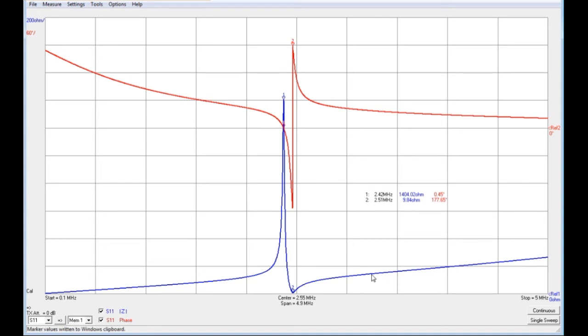So now this is typical of the characteristic of a primary coupled Tesla coil, so two resonant coils together. Obviously the self-resonance of the primary, I haven't got tuned here with a tuning capacitor, so its self-resonance will be at a much higher frequency. We see it was even much higher than the 25 megahertz. So although we saw the magnitude of the impedance peak for the primary, the big one in the center, we didn't see the phase change, which was off the top. Because there's no parallel tuning capacitor on the primary at the moment, it's basically just open. So we have an inductive coil.